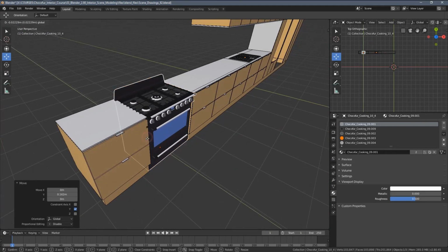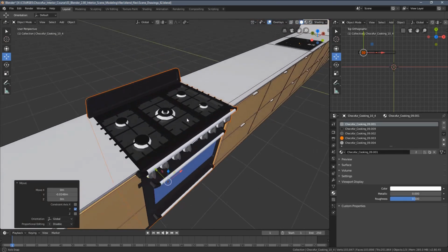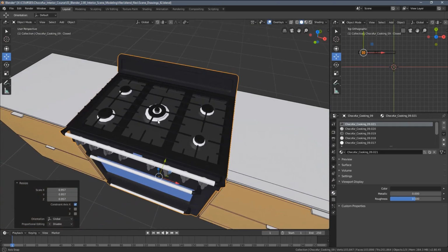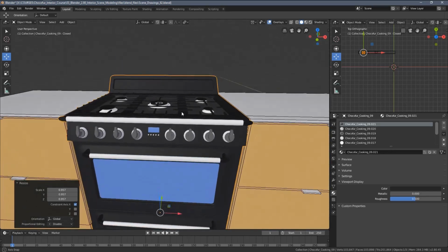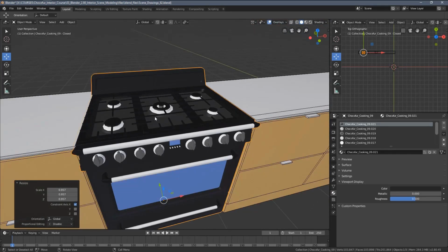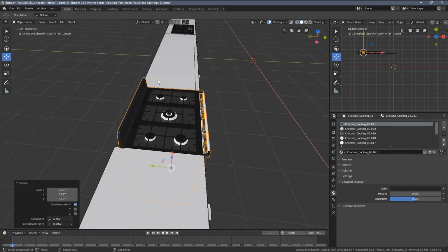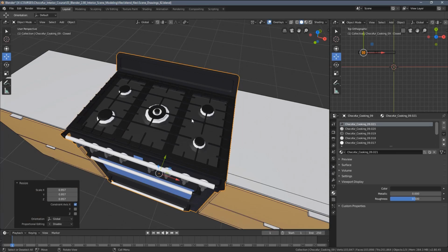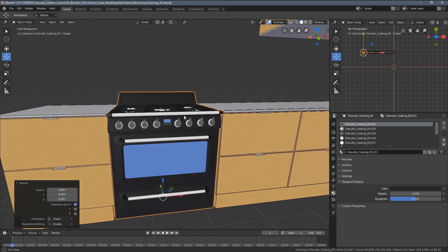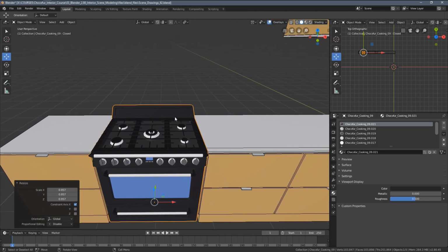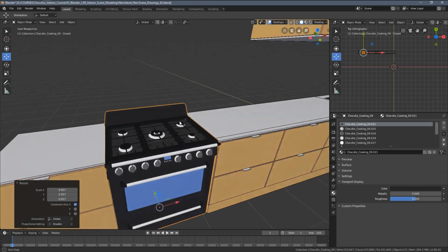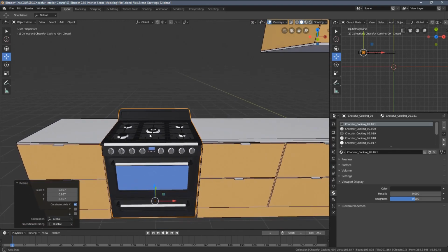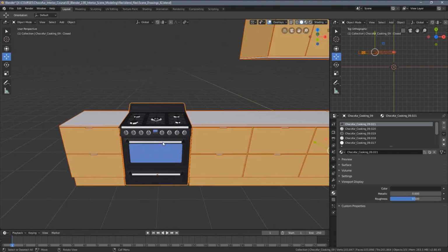And yeah, let's now import another model. Before we add it, we could at this point perhaps adjust the surface a little bit, reduce the geometry, which will not be visible, but I'm gonna skip that point. I just want you to be aware, because we are gonna put a cover on top of this cooking panel here, so all of those details won't be visible in the rendering. And in case you have a lower memory capacity on your graphics card, that could be helpful in case you're running out of memory when rendering. Yeah, but in any case, let's now import a second model.